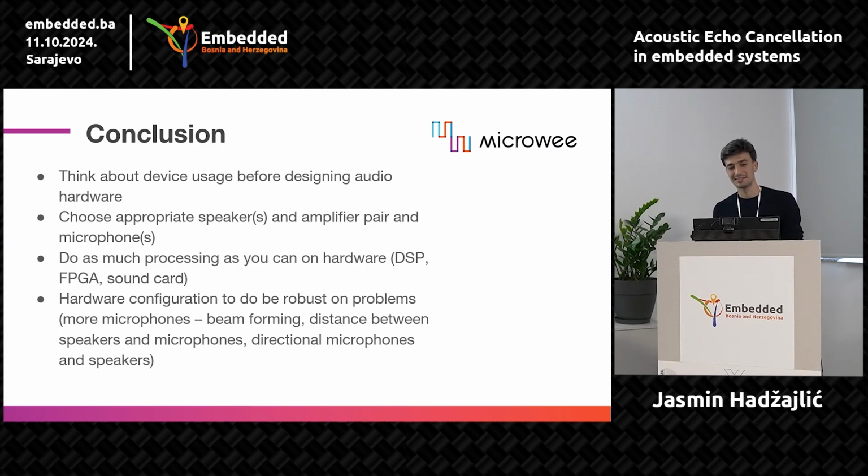Also, while doing this task, we were researching other alternatives, and some advice out there is to use more microphones and do beamforming, and by that you can cancel sound from a specific direction. For example, you have one speaker and 3-4 microphones, and then you can detect from which direction that speaker is playing and cancel only that, but hear everyone else in the room.